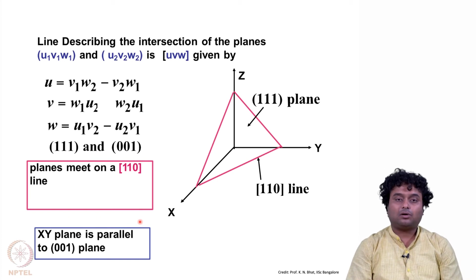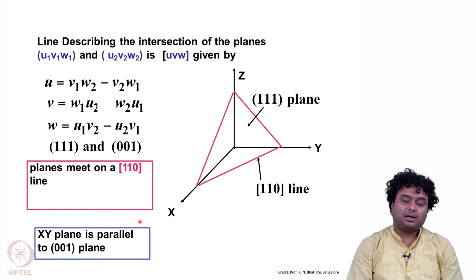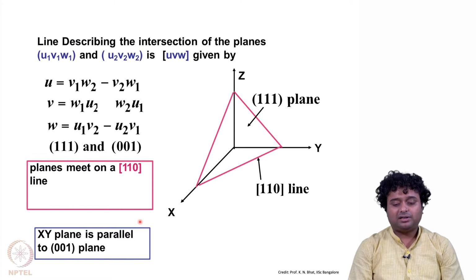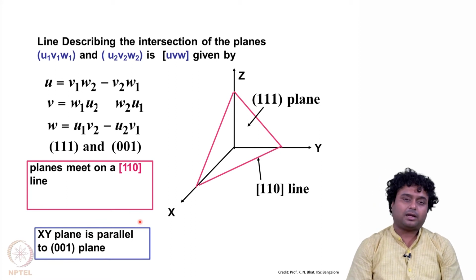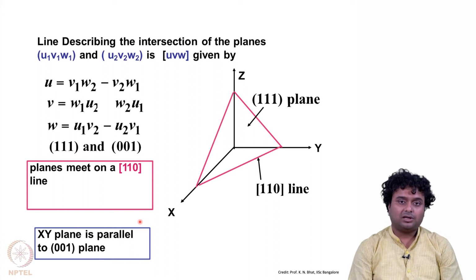Now the important point is that all of these planes are called the 100 plane family, and crystallographic direction wise they all have similar material properties, like we discussed earlier, that in different directions the atoms are connected to the bulk by a different number of bonds. In this family of planes, an atom at the surface, if the crystal is cut in the 100 plane, will have the same property as if the crystal was cut in the 010 plane or in the 001 plane.